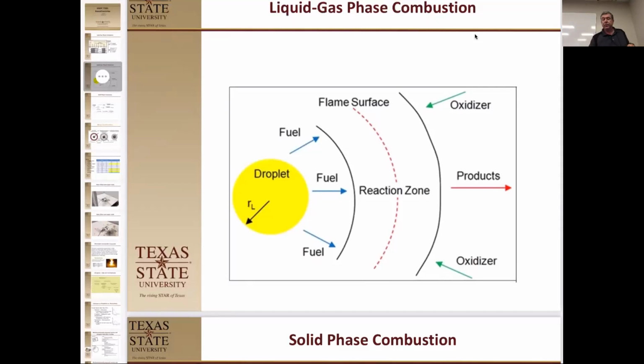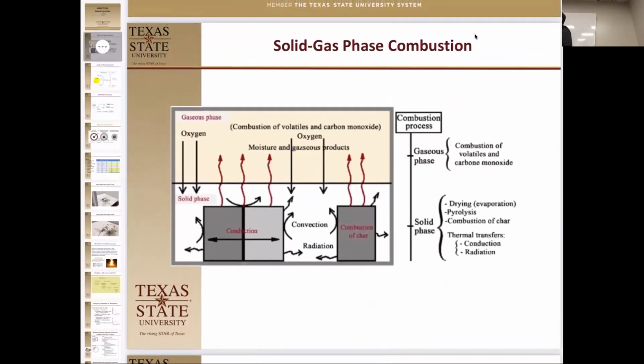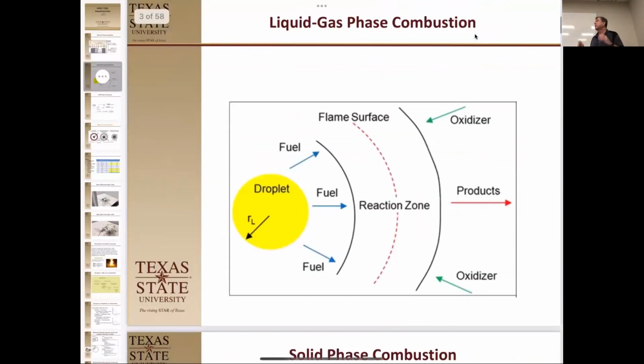Okay. So, but I wanted to talk about combustion because combustion and detonation are two different things. And so I wanted to talk about combustion first. Okay. So droplets, actually, this is like jet fuel or anything that comes out of the droplet. In fact, I published in this and where you can add nanomaterials to the droplet here. If they absorb IR radiation, it increases burn rate because the radiation is coming back, hitting those little droplets, increasing flame rate, and you actually can double the burn rate of a droplet with a nanomaterial. But I'm not presenting that.